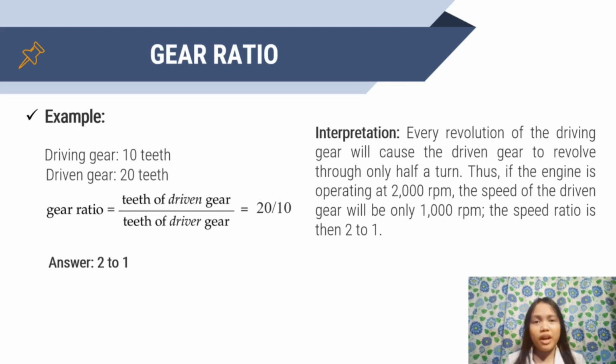Depending on which of the driving and driven gear is the larger and which is the smaller, and consequently which has more teeth and which has less, the resultant gear ratio can produce output speed and torque which are increased or reduced with respect to the input speed and torque. Additionally, as there is an inverse relationship between the two values, either speed can be increased or torque can be increased, but not both. A higher gear ratio equates to high torque and lower speed, while a lower gear ratio associates to low torque and higher speed.